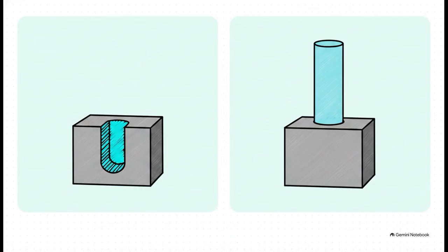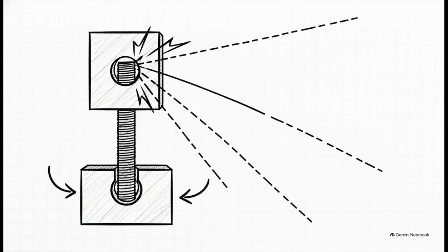Think about it. You've got the surface tolerance, that's the physical depth of the hole buried inside the material. Then you've got the mating height tolerance, which is that functional, empty space floating above the part where the fastener actually lives. The crazy thing is, when we just slap a standard position tolerance on a drawing, we're only controlling that first one. We are strictly limiting our control to the depth of the threaded hole itself, totally ignoring where the bolt is going.